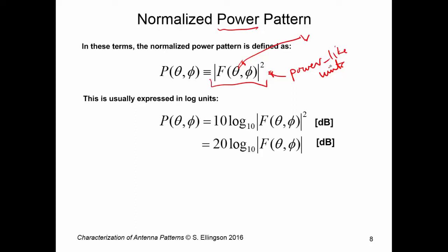This is usually expressed in log units in most engineering applications. So we'll describe the power pattern in dB in the usual way, 10 log 10 of the power-like units, or 20 log 10 of voltage-like units. So you can either square before, or you can square after, whatever suits you.